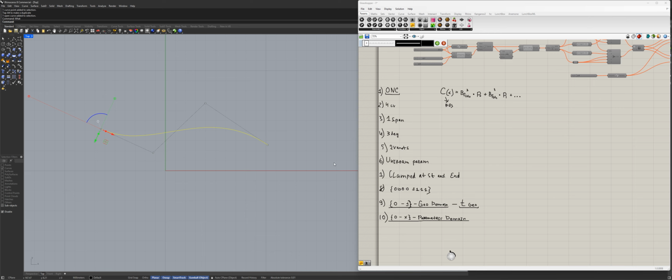So the domain, the parameters, the vector nodes, the t value, the t geometric value, are set up in the process of construction. When the curve is already constructed, you can't change that. It's already built in, because as you're going to see, by moving control vertices I'm changing the curve, but its parameterization stays the same. And even though I don't see the geometrical domain, which, trust me on this one, stays the same, the parametric domain didn't change either. So what is the parametric domain?